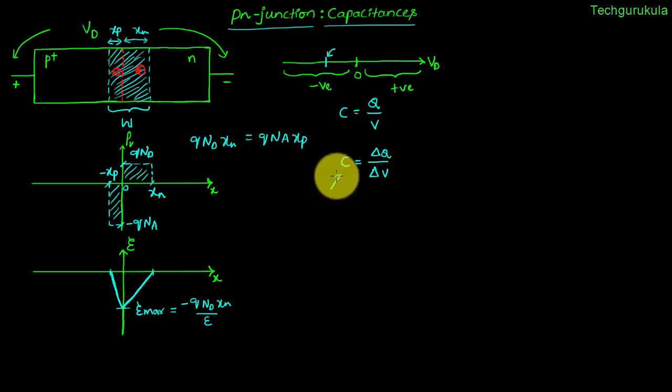And this capacitance, we would call this as small signal capacitance, because practically when we use PN junctions in analog circuits, basically we apply a DC potential for biasing, and on top of it we apply a small signal which is AC in nature. As a result, we are modeling the PN junction capacitance according to small signal, so that in analog circuits we can use this model.